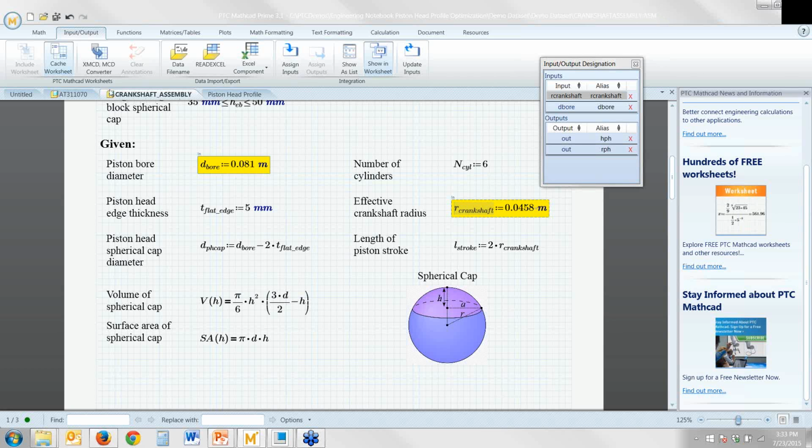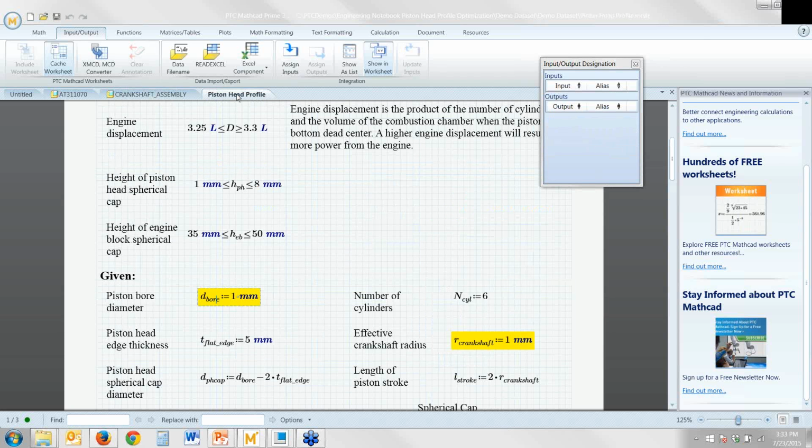The icon also looks like a Creo assembly icon, and the changes that we made in the Mathcad worksheet inside of that model are not reflected in the version of the Mathcad worksheet that is stored on the disk. The moment you create that, the contents live inside of that Creo model.